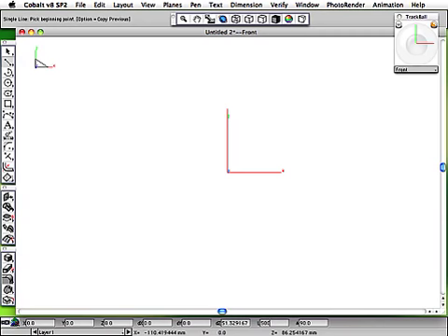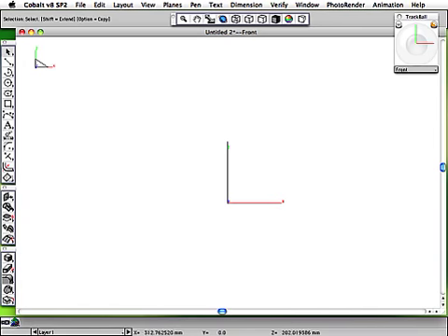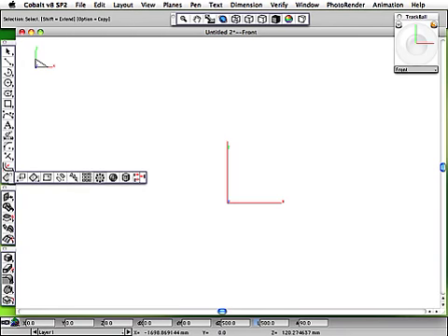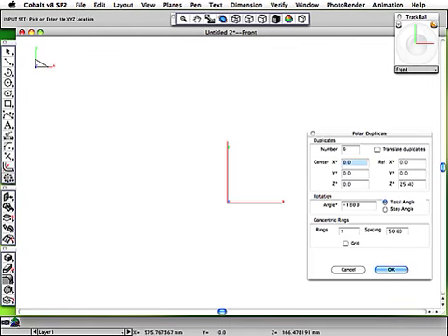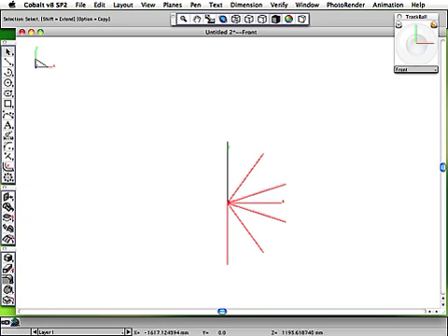Okay, so I'm going to make a lofted surface using the net surface tool. Starting off by making a skeleton structure that I can put some splines on. So I've got a vertical line there which I'm going to rotate in 6 pieces, minus 180 degrees, about the origin.